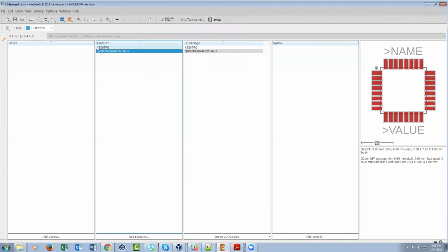Don't you have to push a new version? I should push a new version, yes. So actually, I hadn't saved my changes. Once you save, you're going to see this appear: Version 1 plus edits. Whenever you see plus edits, that just lets you know that there are changes that have been made locally that have not been pushed to the cloud.